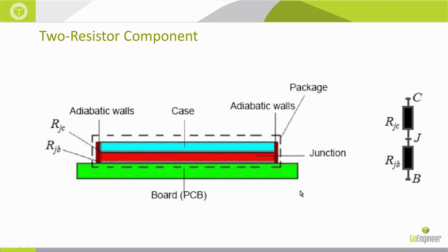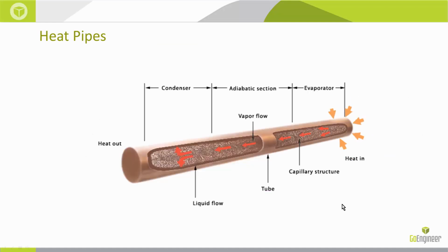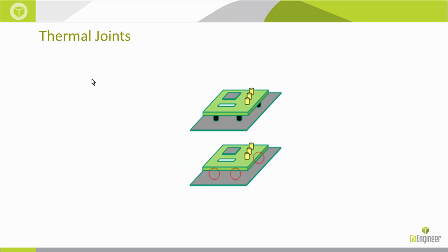Next up is heat pipes. Heat pipes are a multi-phase system, and we cannot do multi-phase interactions inside of flow simulation. So we represent them in SOLIDWORKS using a simple cylinder with heat transfer from the inside face and the outside face. We assume the fluid movement through the center is so quick that there's no heat loss through the walls. So if you apply a heat pipe to your cylinder, you're automatically going to have insulated conditions on the outside faces.